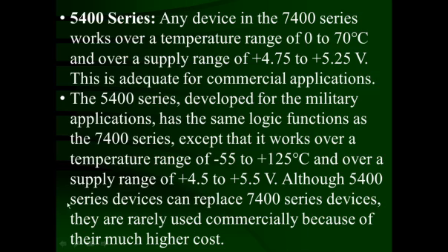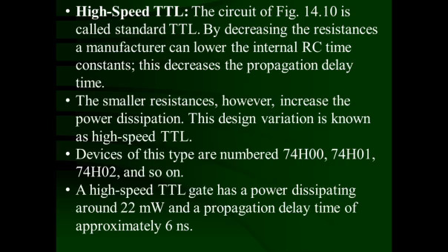Although 5400 series devices can replace 7400 series devices, they are rarely used commercially because of their much higher cost. Military versions have the same logic functions and number of inputs, but their temperature range is larger and they can tolerate a slightly unregulated power supply, hence these ICs are costlier, and we don't use them for commercial purposes.